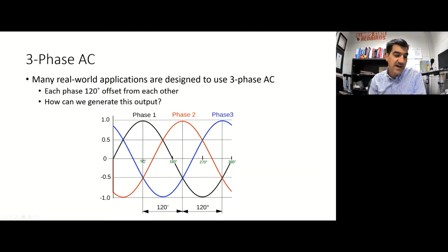All right. Sometimes I will note that you'll see wires in groups of 3, but then also you'll see a wire on top of the transmission lines. That's called a shield wire. Basically, same thing as a ground wire, but the idea behind that is that if it gets struck by lightning, then the lightning would hit the shield wire, which is just grounded, and it would conduct the lightning just down to ground, and it wouldn't harm the electric grid.